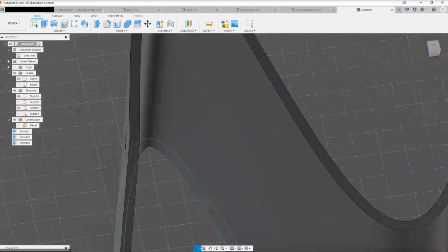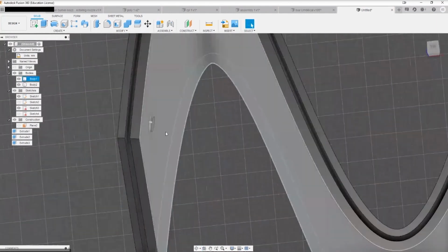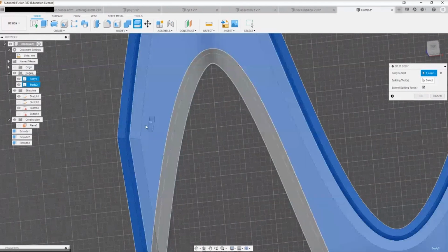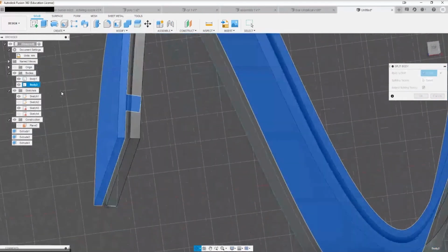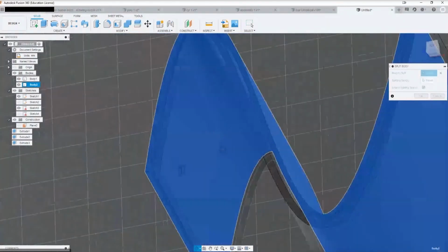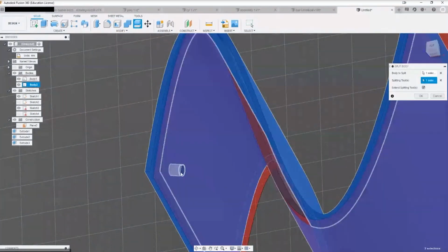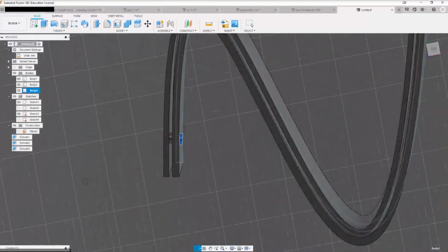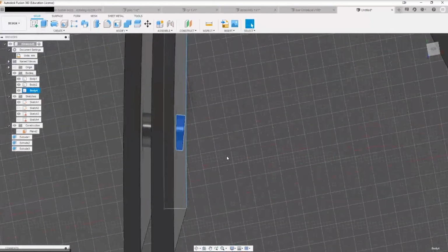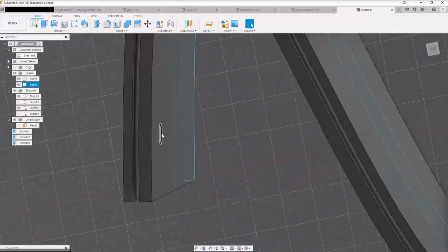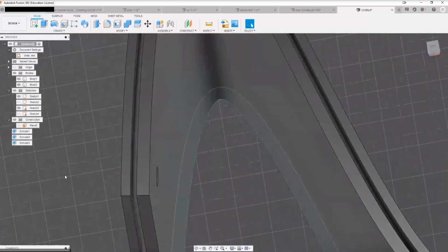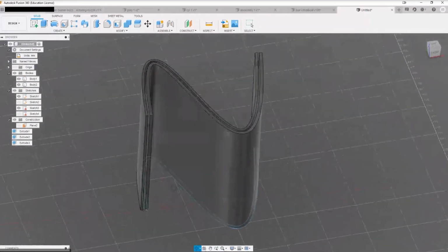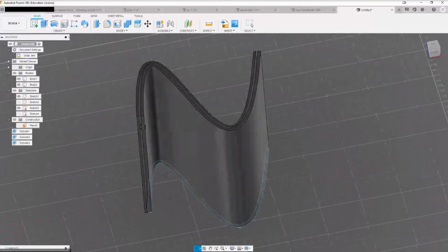Now you can see there's a hole that's attached, and for example, if you want this to be flush, we can use that split body thing. So now we select this body, the initial one that we had that's in blue, and then tool, which was that outer surface, just so we cut off that excess. You can use that. So you can see that bit's left over. You can happily just delete it, and now everything is nice and flush. Okay, cool. So let's just say this is a basic assembly, right? So you've got one bit fitting into the other.